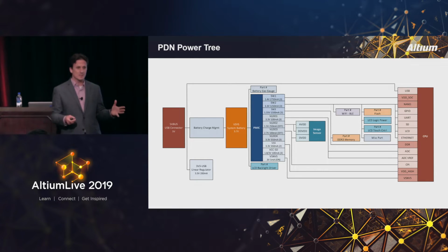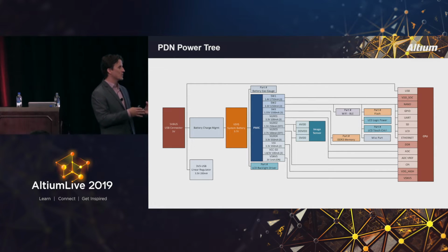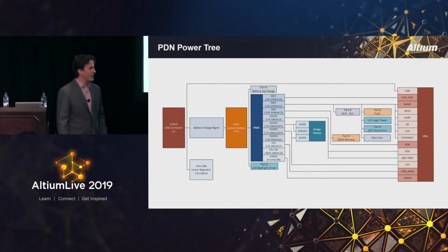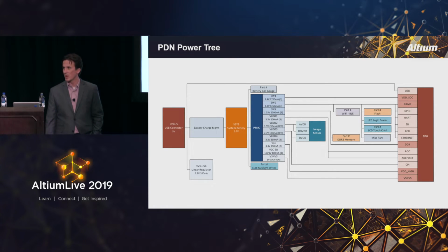And sometimes we go the other way, though, where we'll try and consolidate the power conversion on a board to one section of the board. But generally I've found it advantageous to bring the power conversion closest to the devices it's supplying.